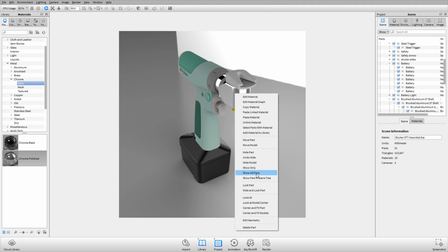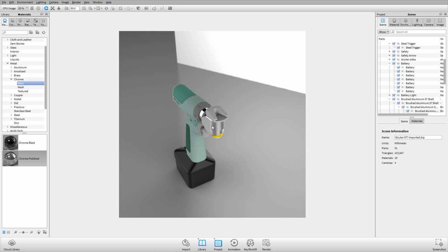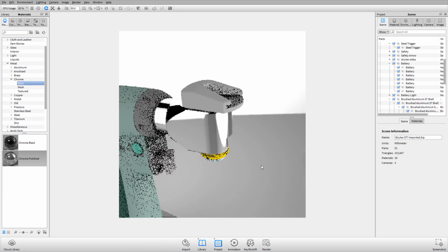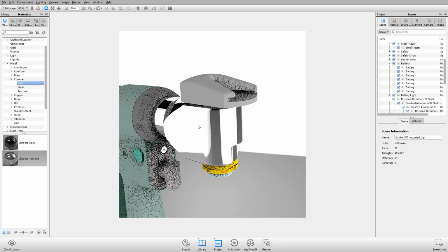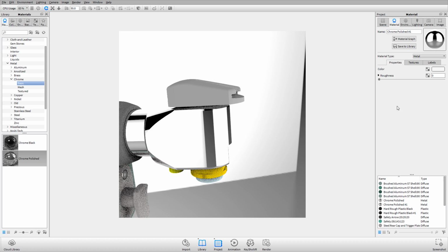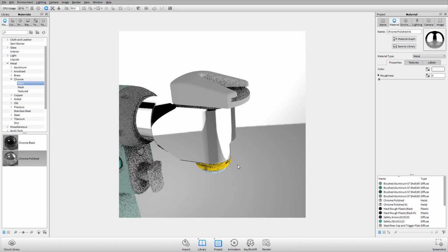I'm going to right click and hit look at. The hotkey for that is Control Alt right click. I'll be doing that while we're working. But if you take a look at this material and I double click on it, that brings up my material editor. And so these are some of the properties that we can change. For metal, it's basically going to be color and roughness. Those are our main properties, not including textures that we're going to talk about.